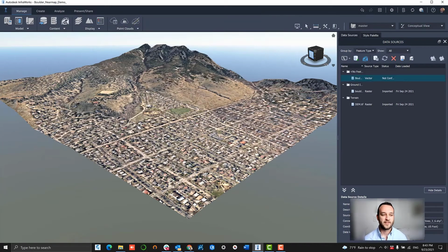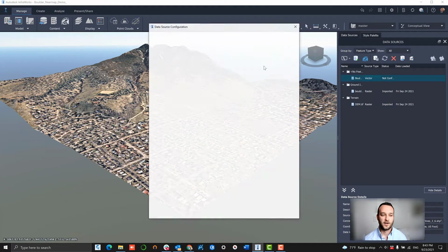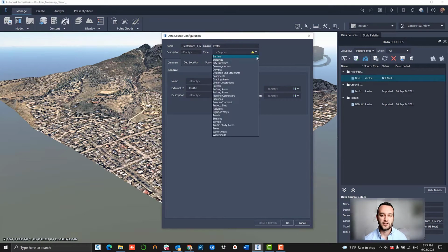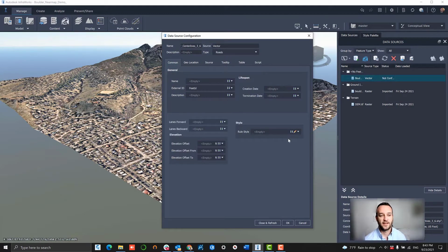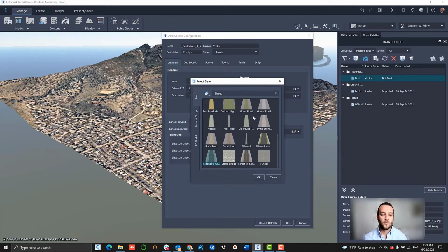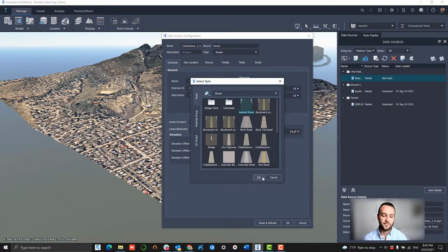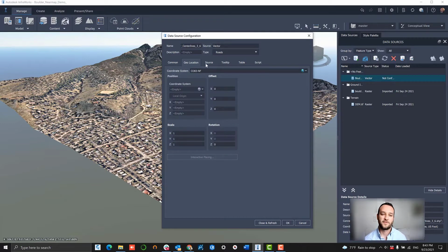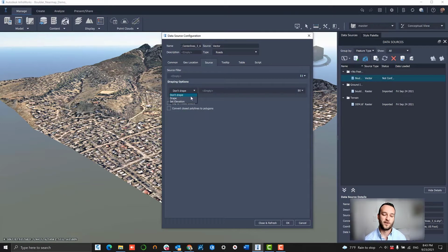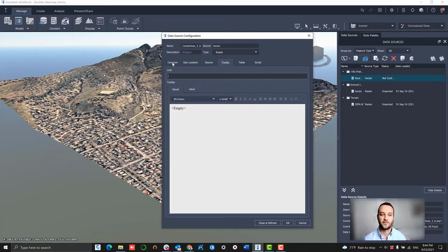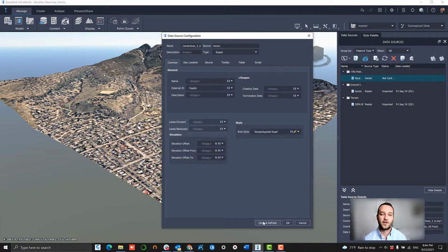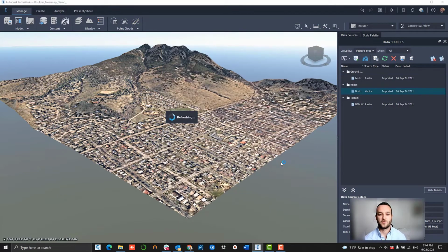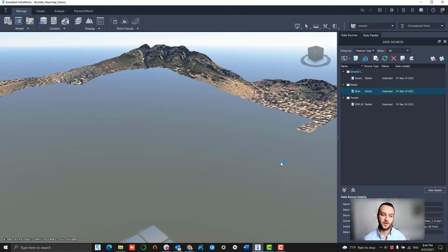So we load this content up by going to our directory here and loading a shapefile that identifies those road center lines. We want to make sure we load that content as the road InfraWorks layer. And then we want to select a style that fits with the environment, so that we already know what that road is going to look like. So here I just have a basic asphalt layer. And then we're going to drape that onto our existing terrain. Since these are existing roads, we want it to match the profile of the ground data that we've already loaded.